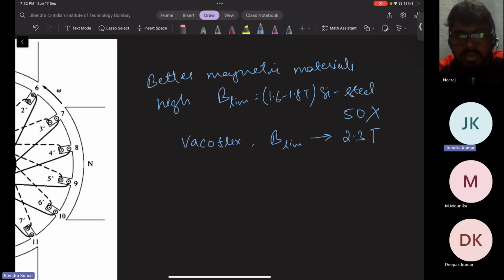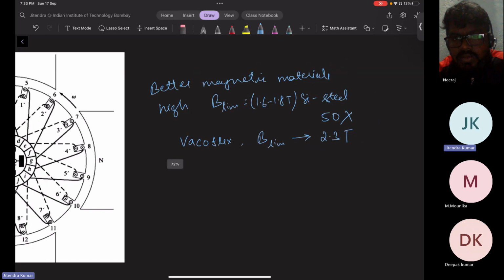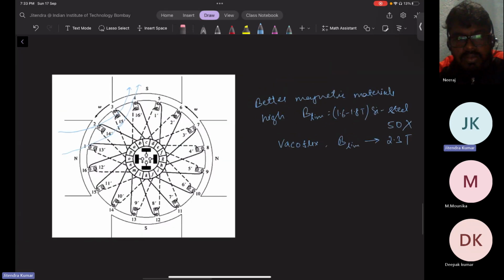So better material means you can increase the magnetic loading, but it does not certainly mean that it will uniformly channelize all the magnetic flux path. It is the work of the designer to design so that all the conductors are uniformly linked. Here comes the job of machine designers. It might be a bit abstract, but in the next session, please remind me beforehand so that I gather some simulation results on the basis of a DC machine, so that you get a better perspective of it.